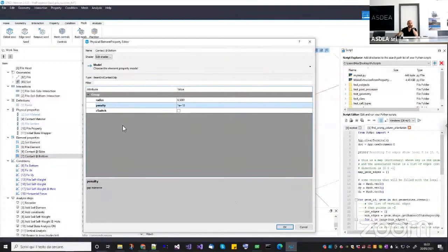Why did I decide to use this cylindrical one? Well, because I will use this kind of example later on in new webinars to assign different kinds of contact elements, and the new kinds of contact elements will need a cylindrical local axis. So for this specific one, it is not necessary. The only important thing is that the x-axis points in the same direction of the beam. But I will use it for the next webinar, so that's why I decided to use the cylindrical local axis.